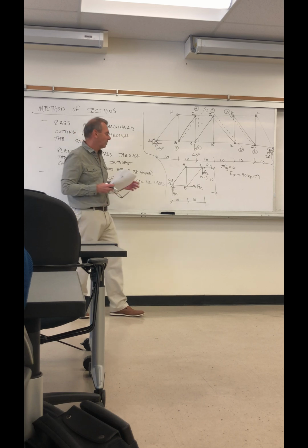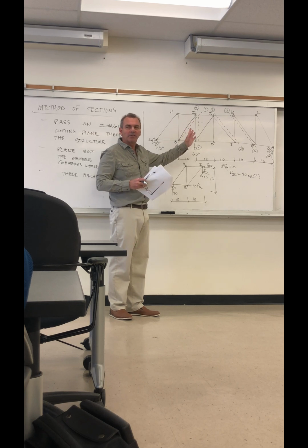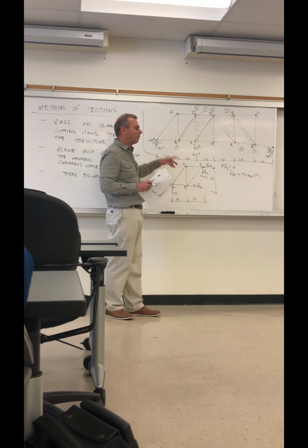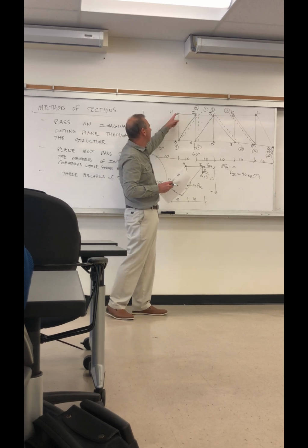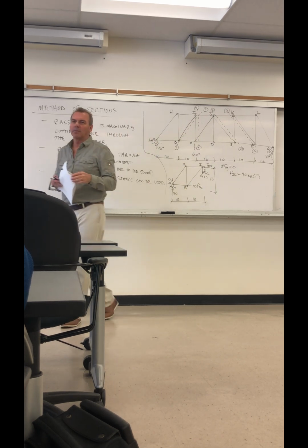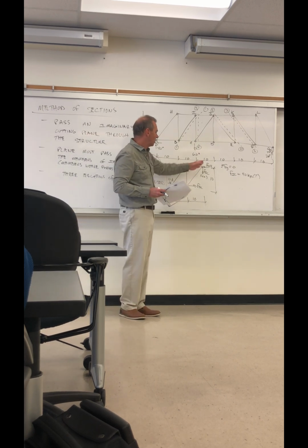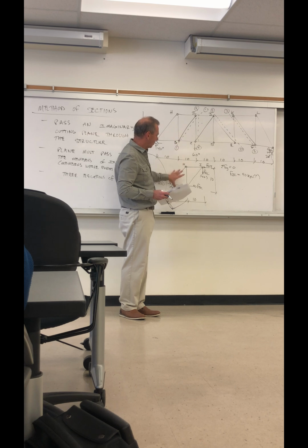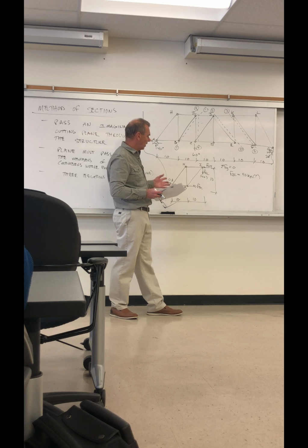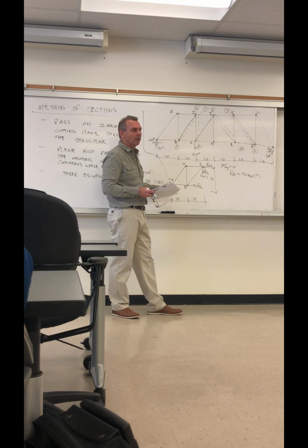Now, if I asked you to solve for that same thing, F of IC, for this problem, and you didn't know method of sections, you did it by method of joints, it'd take quite a bit of work to get out there, right? You would start from here, and then go to here, and then to here, and then to there. So it'd take you 20, 25 minutes. With method of sections, there are no calculations even required. You cut it, you redraw the structure, and you can see by statics there's no other force in this picture than this 40 down, so it has to balance the 40 out there.